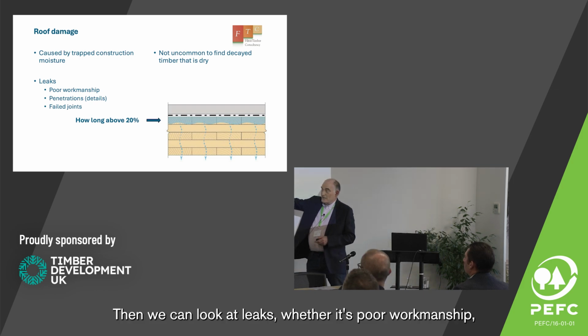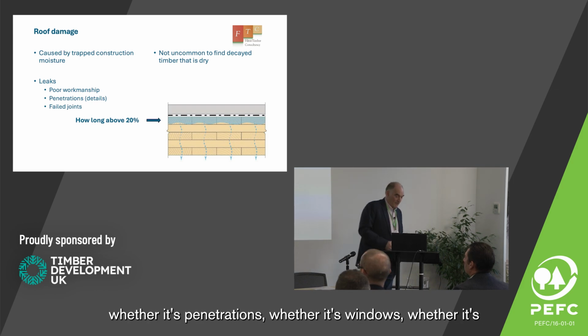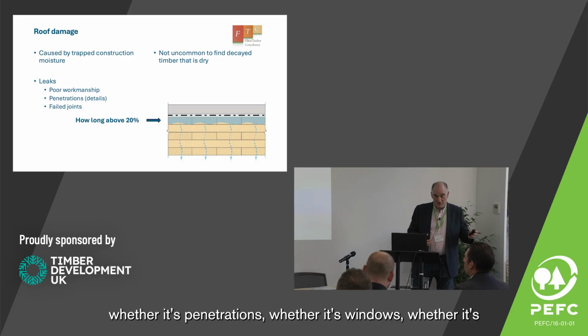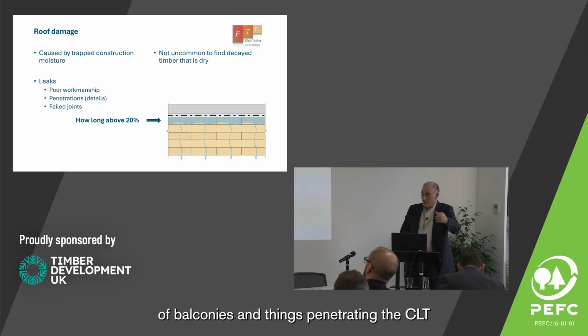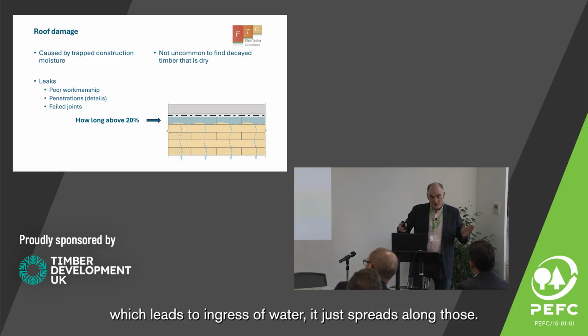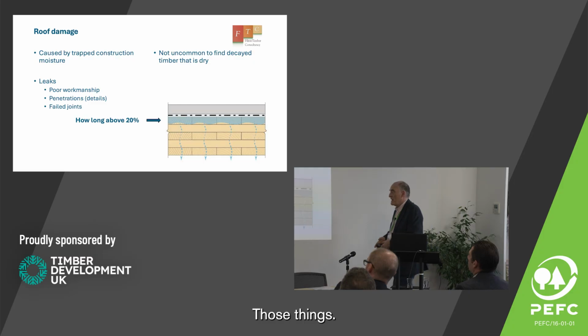Then we can look at the leaks, whether it's poor workmanship, whether it's penetrations, whether it's windows. We've seen balustrades of balconies and things penetrating the CLT, which leads to ingress of water. It just spreads along those things.